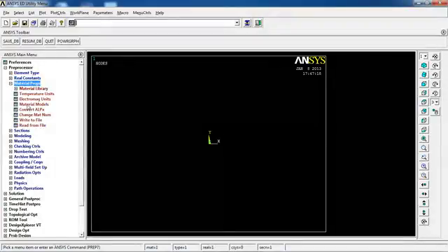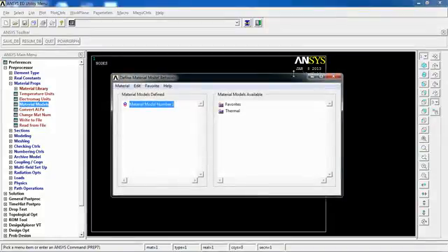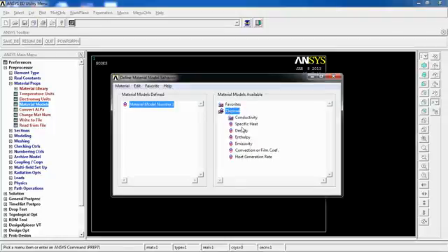So I click on Material Models, and what I will see is this new window, which is different from structural in that the properties that I can define from a material in here will be only thermal properties, and so this window does not ask me for elasticity or Poisson's ratio. The only thing that is asking me is about conductivity.